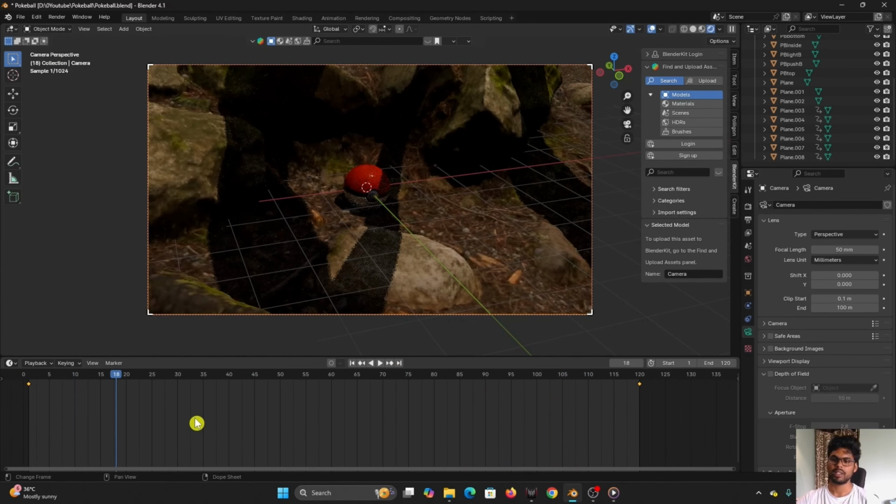And also you must see that the animation starts out slowly, then it speeds up and then ends up slowly. And that is pretty much a Bezier curve. But if you want a linear animation, because in case of cameras, it really works, it looks organic when you're doing this for organic objects like leaves and stuff. But in camera, I'd always prefer that it be linear.